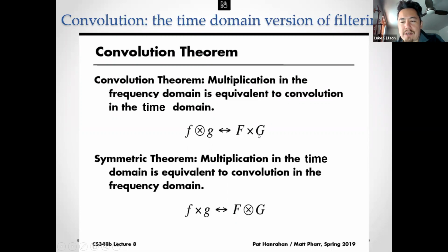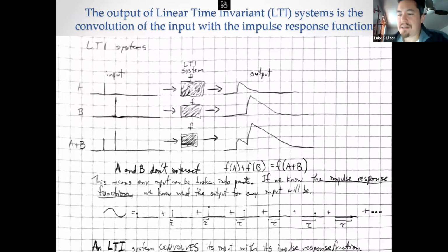So what that means is that we could either Fourier transform stuff, multiply these things together, and transform it back to filter something in principle, or we could convolve f with essentially the Fourier transform of the filter's transfer function, which is often called the convolution kernel, or the filter's kernel. I'm not going to write down the equations because I think it's not even necessary, but just to give you a conceptual idea of what convolution is like, this is kind of messy, I just wrote this out.